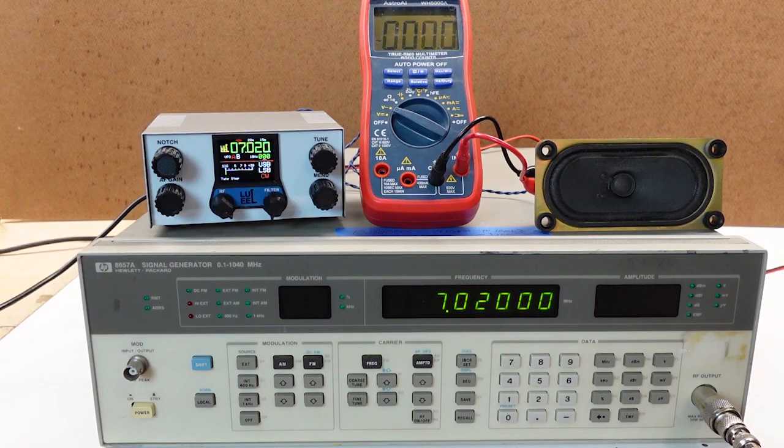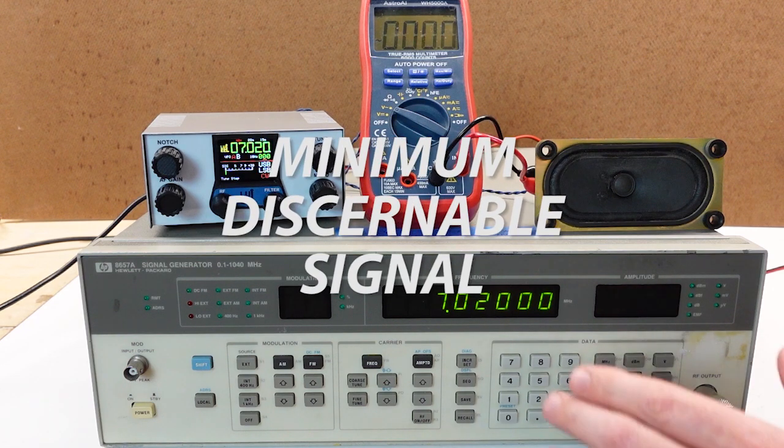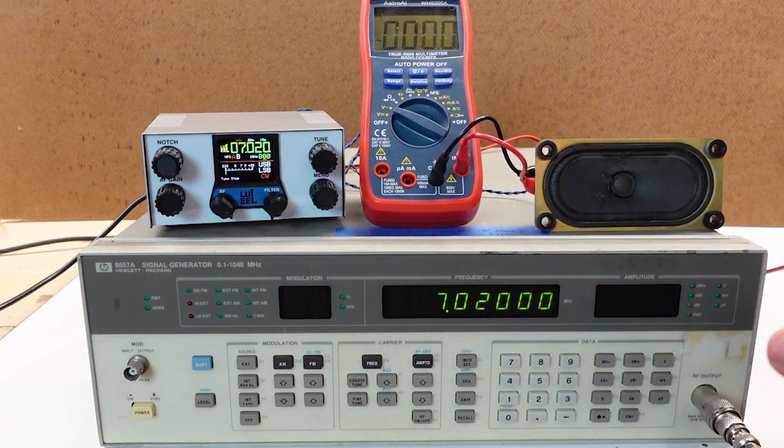I'm going to perform a common receiver test. It's called the noise floor test, or sometimes the minimum discernible signal, or MDS test. And it's very common, like I say, to run this on a receiver. And basically, it's trying to quantify the weakest signal that you could say that this receiver could pick up. And by quantify, I'm actually going to take a stab at getting an actual number in dB.